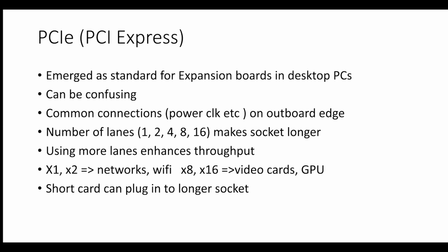However, if you open up your computer and you've got an X4 PCIe card and you've got a big long socket, you can plug it in and it'll work. The power and the clocks and all that good stuff on the little bit will make the board work. You're just wasting half the bandwidth in that socket, but you can plug a shorter card into a bigger connector. You obviously can't connect a big long card into a short connector because it won't physically go.